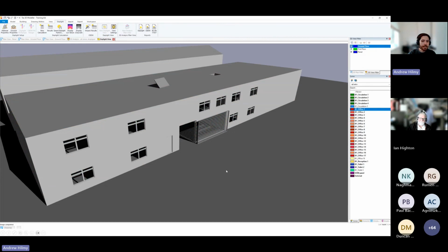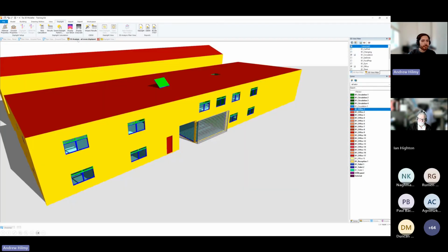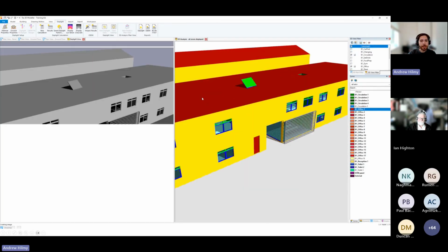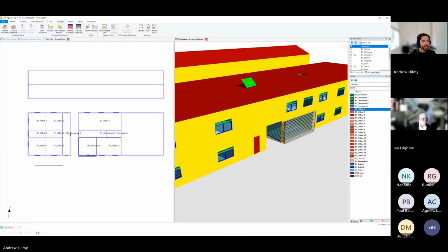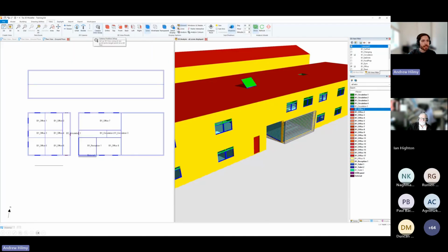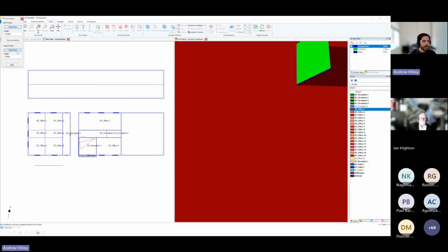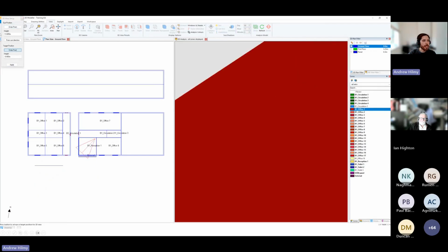And then this does a much more accurate projection of all the shadows, using the daylighting engine. Another handy trick you can do is to use the 3D view here to position yourself nicely within the space. So if I go to the View tab and press Camera View Setup, I can pick the eye position where I want to be positioned and the target position where I want to look, and then set the height of the camera.